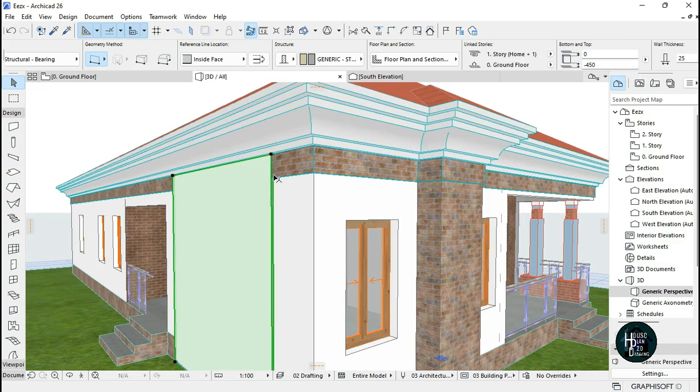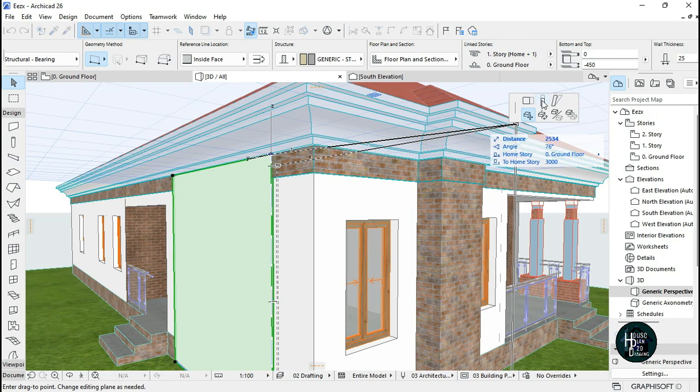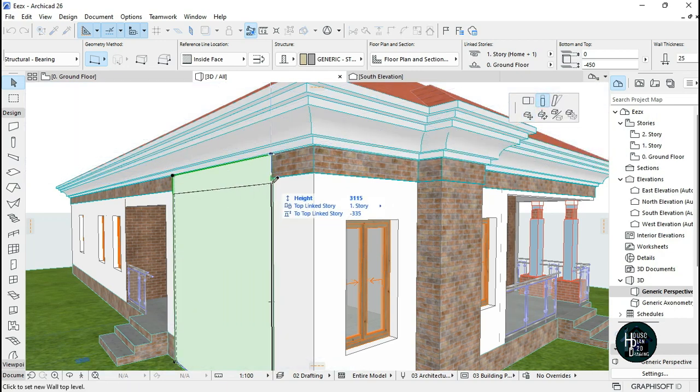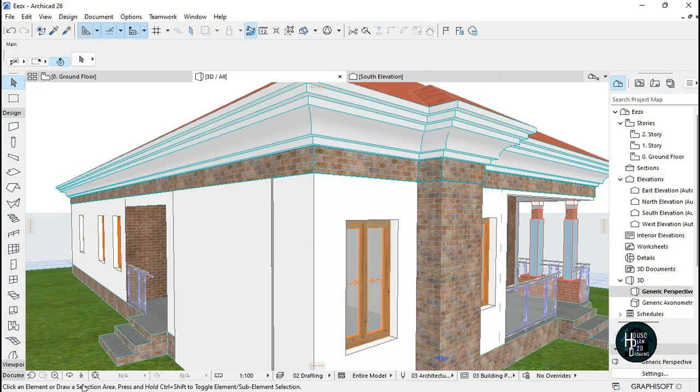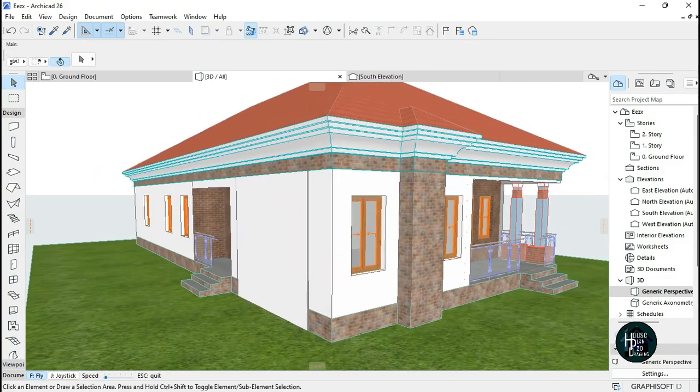Okay, and I also want the design to stop around the side here. So I'm going to click on this black node. Make sure you're selecting the stretch. Come down, hold down shift on your keyboard and select this point here. So it's just gonna look like that.